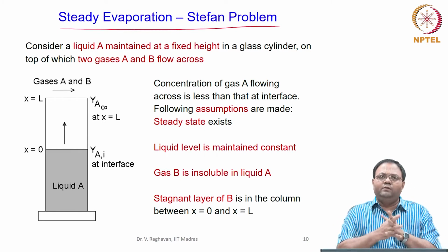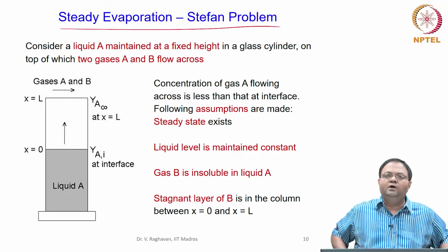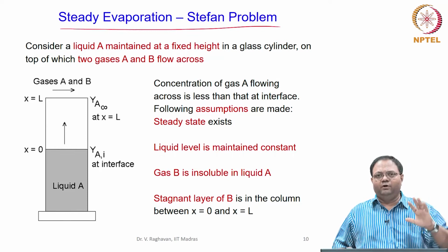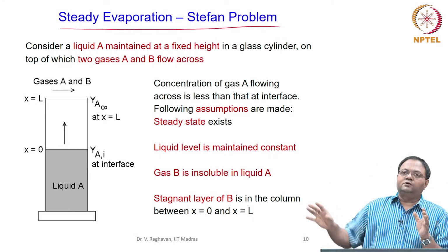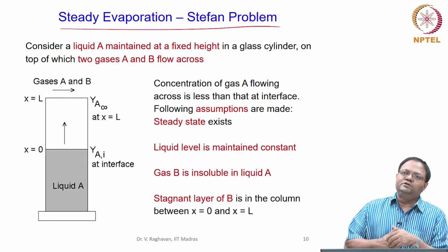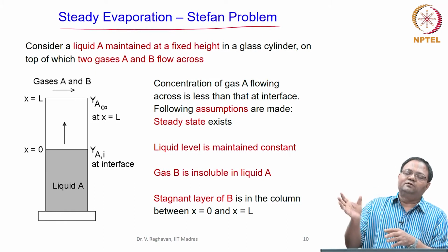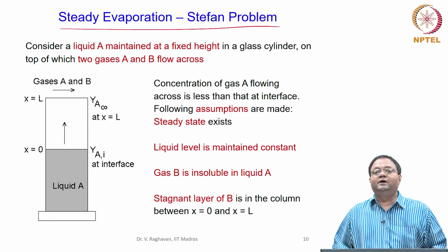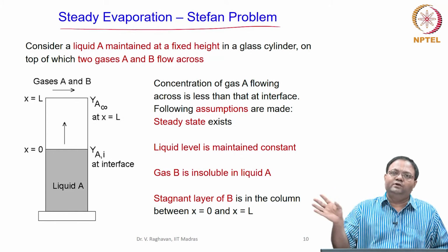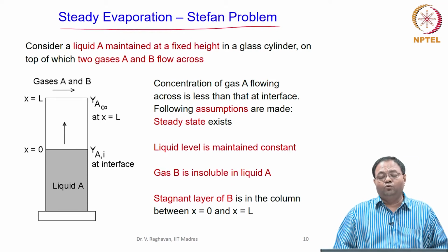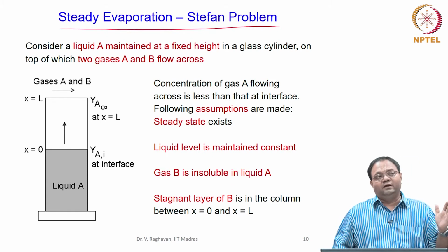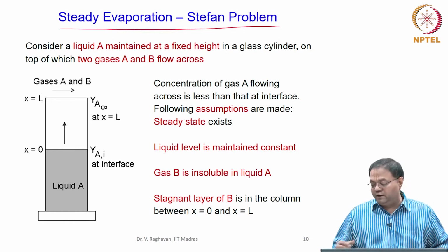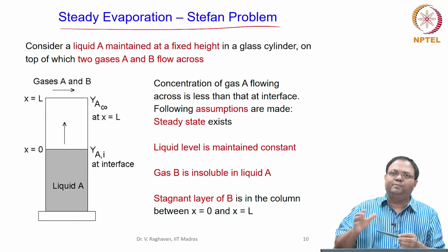Now, let us consider the first example. Till now we are only dealing with the gaseous mixture. Within a gaseous mixture, how the diffusion can take place because of the gradients. So, for example, if air is flowing in a horizontal duct, and as a cross flow a fuel is injected, you can see how the fuel and air mix. Initially at the point of injection the fuel concentration will be higher, and it is first partially carried by the air, and it also diffuses towards the direction where its concentration is low. In several scenarios, when the convection is higher and higher, then the diffusion contribution will be lower, because the convection will suppress the diffusion.